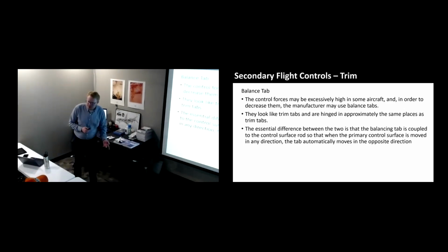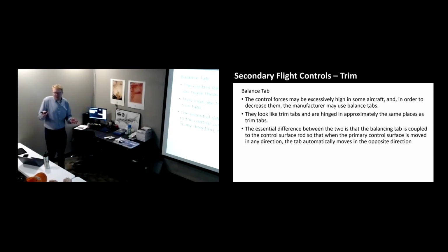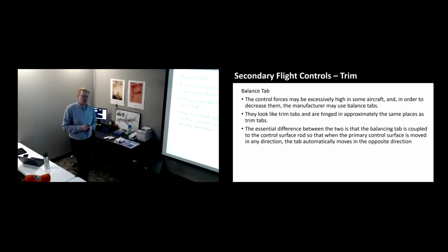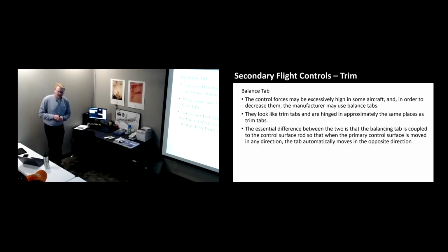What do the weights do? Is it drop it down? Yeah, balance the aileron out a little bit. They can also adjust the physical aileron's neutral position while sitting neutral as well. We'll adjust those things on the ground. The maintenance manual has a set angle they should all be sitting at, and they'll put a little angle measure on them to set it.